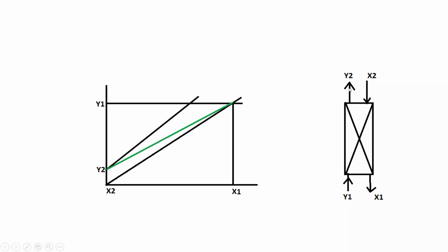So you can see here Y2 will be less, so we will write this Y2 and X2, and Y1 will be higher, so we can say Y1 is this, and X2 is here, X1 is something here. But whenever we calculate the minimum solvent flow rate, then we need to touch this line at equilibrium. It will touch the equilibrium line. At this point, we get the minimum